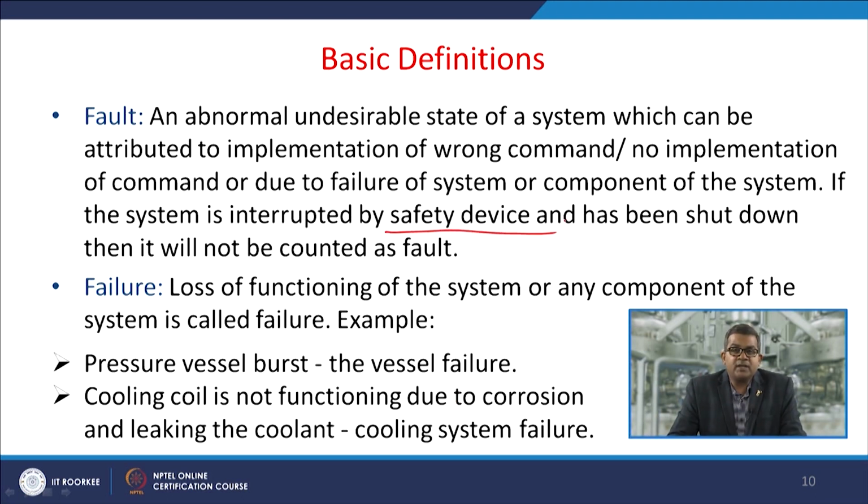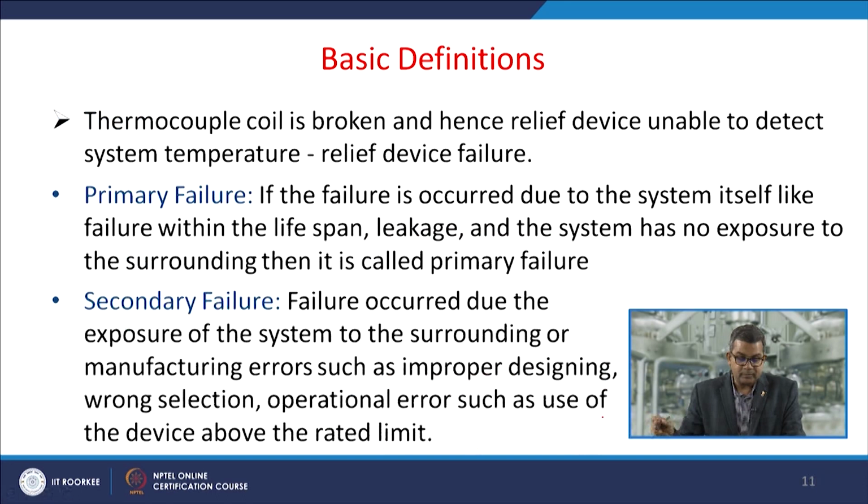Now failure is the loss of functioning of a system or component of the system. For example, let us say if the pressure vessel bursts, that is a vessel failure. The cooling coil is not functioning due to corrosion, sometimes leaking, sometimes lack of pressure, etc. So sometimes the cooling system fails. Now sometimes it may happen that the thermocouple coil is broken, hence the relief device is unable to detect the system temperature. So it may be termed as a relief device failure.